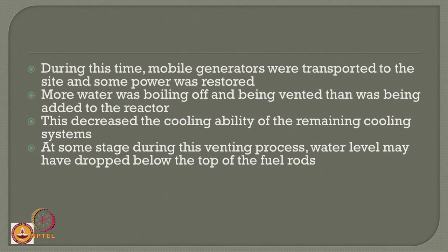You need a lot of water; the amount of water required to cool the reactor is enormously high. At some stage during the venting process, the water level may even drop below the top of the fuel rod, and the fuel rod is at a very high temperature, as high as close to 2200 degrees centigrade. So, they need to be cooled down.